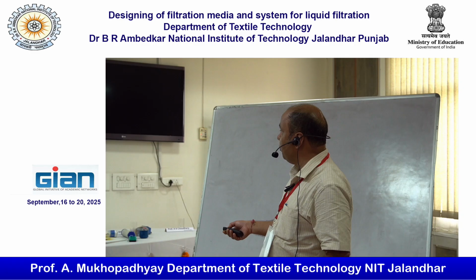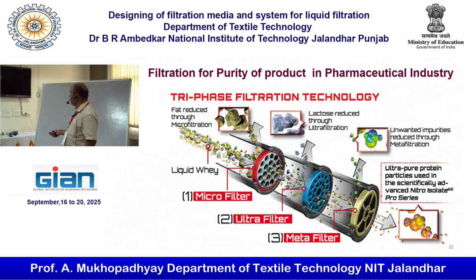Now you can see the purity of the product in pharmaceutical application. Basically we want to get the protein powder, but in the process you have a three-stage filter. One is the microfilter, second is the ultrafilter, and then the nanofilter. You remove the lactose, and through ultrafiltration unwanted impurities are also reduced, so as to get the protein powder out of this whole system.